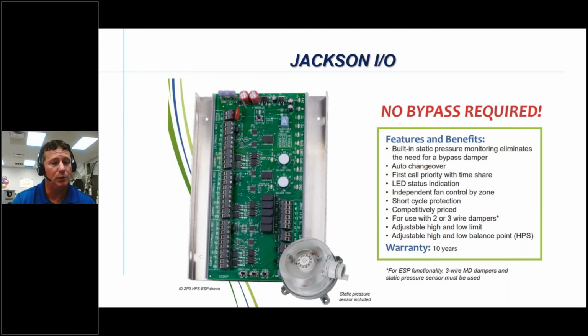So yes, you do push a little bit more air into zones that are not calling, but we're only talking fractional, only enough to affect our total external static pressure that is on the entire duct system, so that we can maintain a constant external static pressure on that blower. Very nice pieces of equipment.